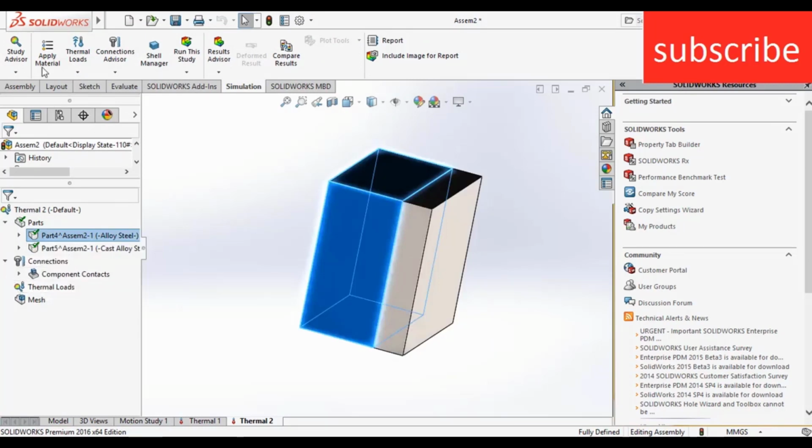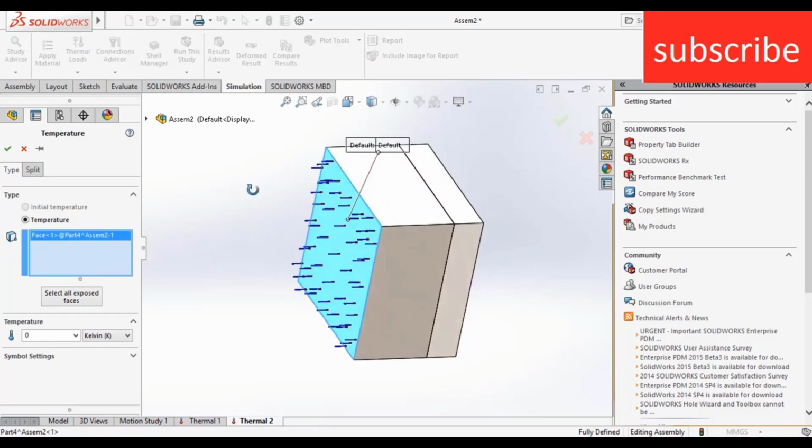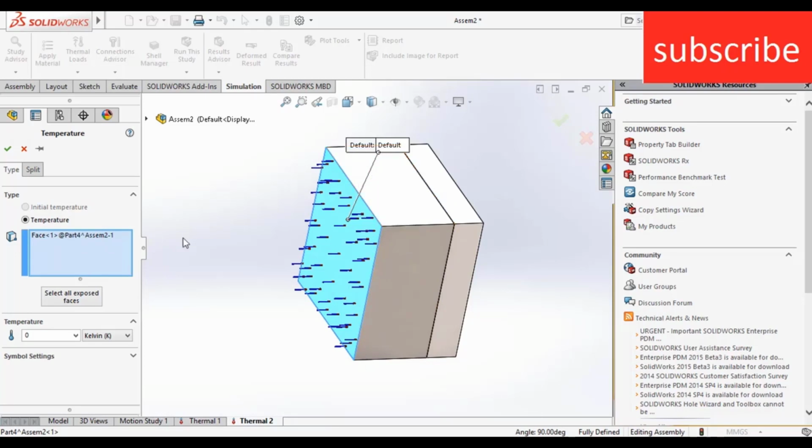Now go to thermal loads, click on temperature, just select this face. A question will arise in your mind: what will happen if I select this face and this face? Just remember, if I select the top face and side face, then my simulation will become 2D and 3D.